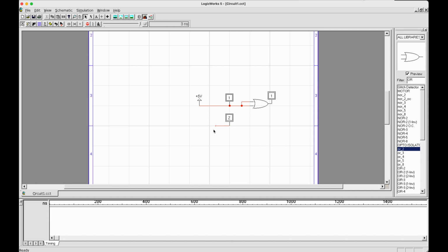On the bottom side, if we want to fix a zero value onto this wire, we will need to get a digital ground. You drag out a digital ground and then perform the connection. You check that it's indeed connected, and as you can see, this wire now carries a negative value. This is called value fixing.